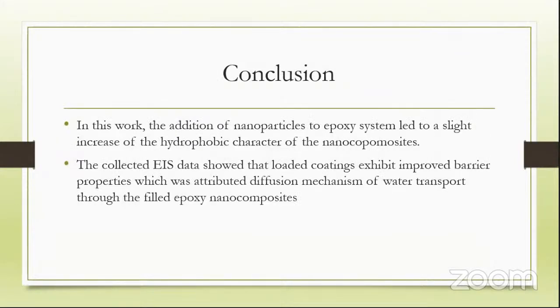And the conclusion was that the addition of nanoparticles to the epoxy system leads to a slight increase in the hydrophobic character of the nanocomposites. The collected EIS data show that loaded coatings exhibit improved barrier properties, which was attributed to the diffusion mechanism of water transport through the epoxy nanocomposites.